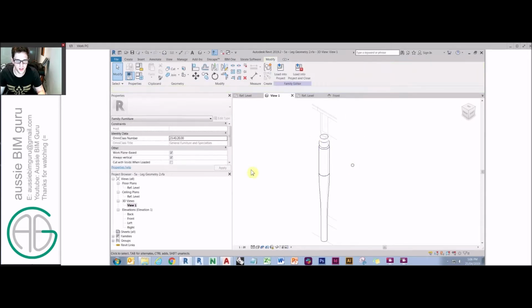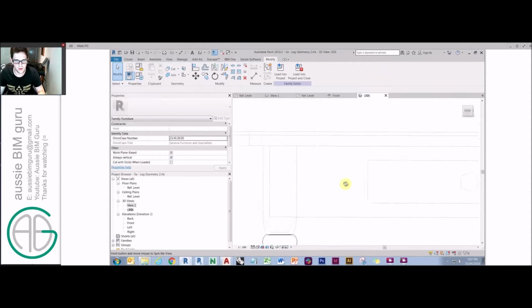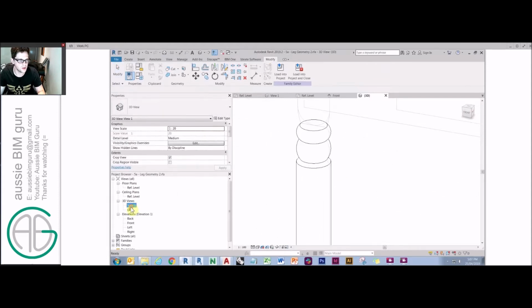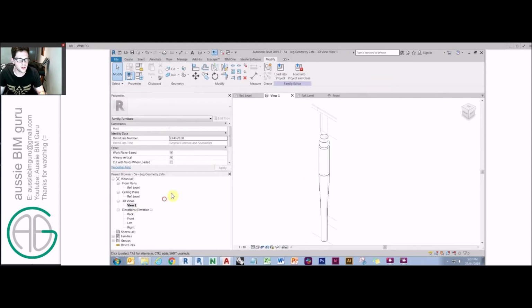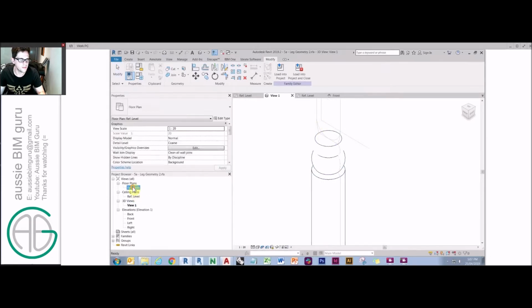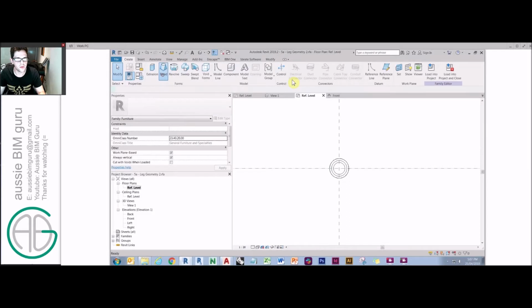Sometimes curves can bug out in 3D a little bit, but when you go to render it, it should be fine. It's just Revit struggling to convey the geometry in hidden format. Okay, the next thing we need to do is do a blend. So we're going from a circle up to a square. So it's a transition of profile.